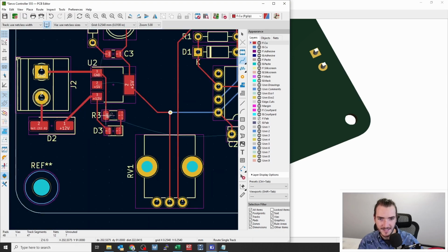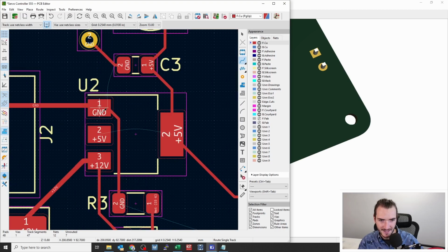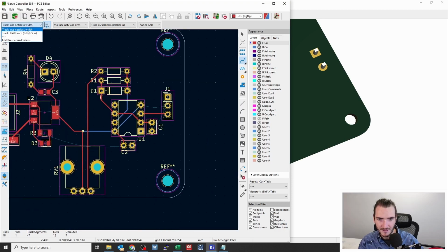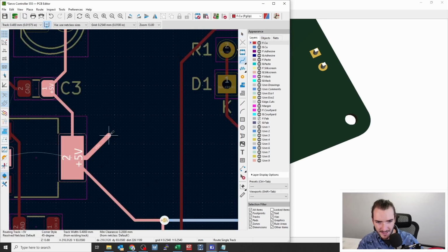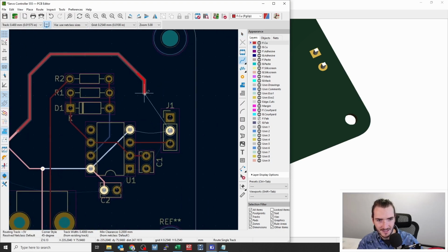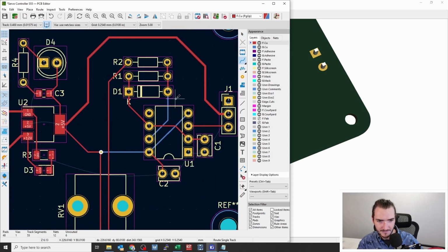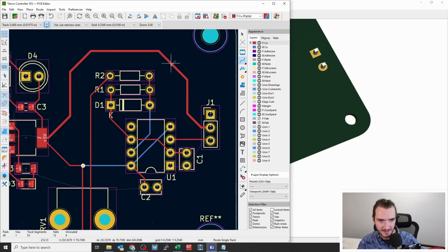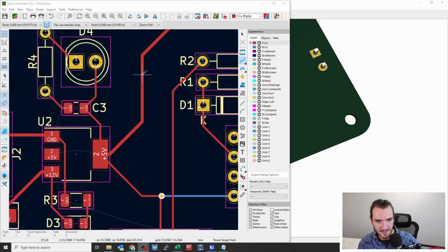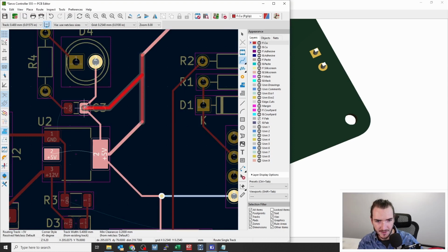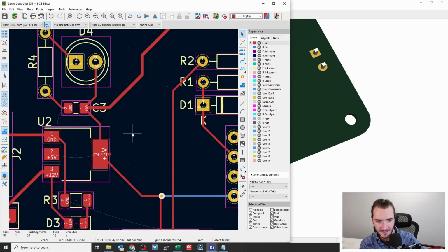There's still a ground connection to make. We'll get to that later. And this one too. Go back to our thick trace. So I've got this dedicated high current path for the servo, and I have this low current path to drive the circuit. It's probably prudent to keep them separate. And I'm even tempted to bring the current path through this capacitor instead. And that way we have a bit of a star topology for power distribution.